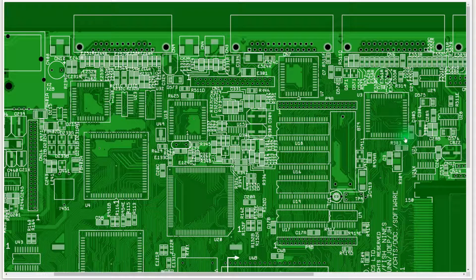So we have the left and right audio out, or actually I guess it's the right here and left audio out here, and then we have that audio ground, which is fed from right here. It's labeled A_ground, it's pin 37. And that audio ground makes its way all the way around. If you look at the filter caps here that we looked at in the power supply, you can see that that comes to the positive on one cap and the negative on the other. It's also brought out to the edge connector down there.